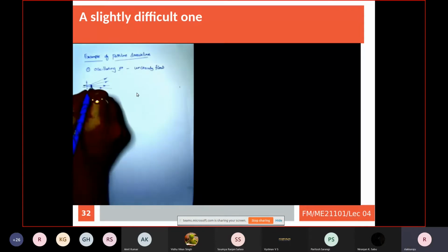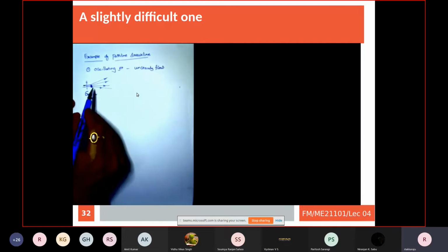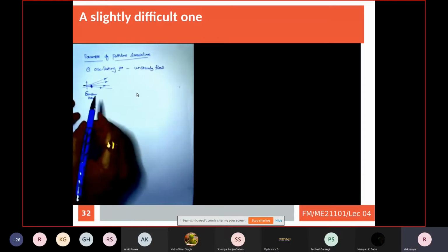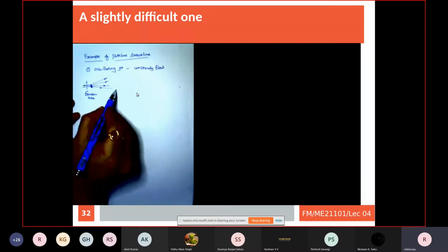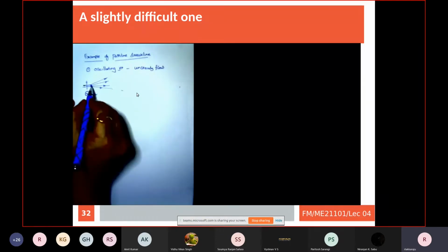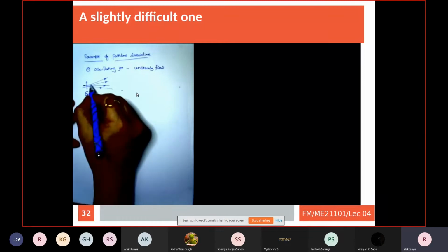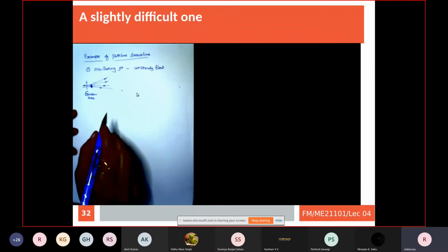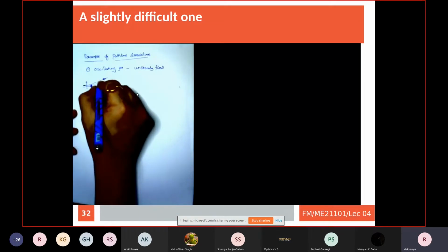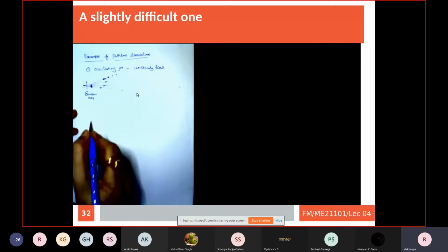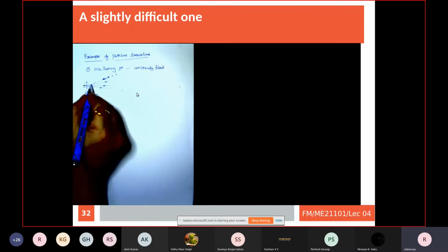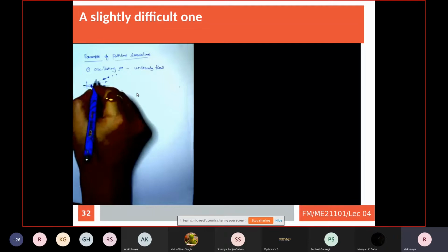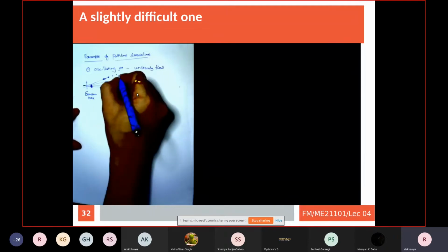You look at any fluid particle which leaves at that location. Once it leaves the hose, it tries to go in a rectilinear way in this direction. Perhaps this fluid particle on another line tries to go in that direction once it leaves the hose. Whether you are shaking it up and so on, once it leaves that hose in a rectilinear way, the fluid particle tries to travel further. The fluid particle which is released there, you are trying to shake it up and down. Once it leaves, whatever tangential velocity it has acquired, in that direction the fluid particle traces. That's what we call a path line.